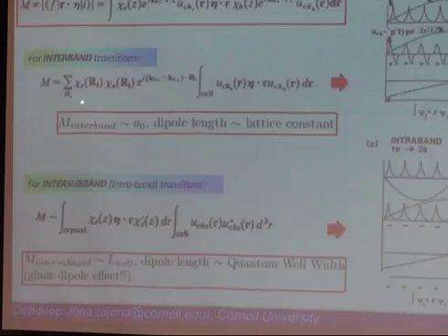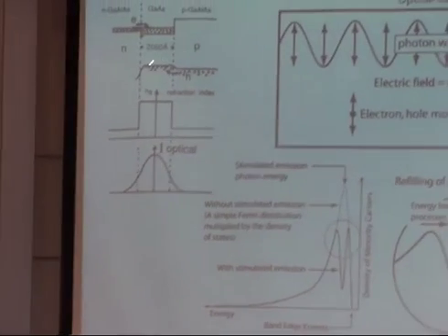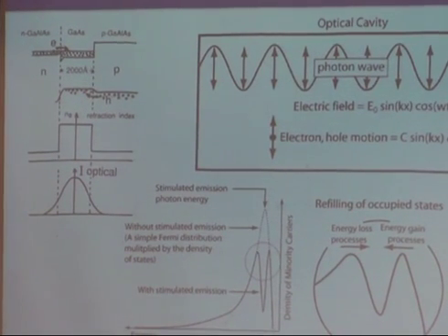Sorry, I'm going to skip a couple of things here. The other thing is I didn't talk much about mirrors, but I think you realize that if I have, say, a quantum well like this, a very thick well, it's not even a quantum well. It's 200 nanometers of gallium arsenide, 2,000 angstroms. These used to be called the DH laser, the double heterostructure laser. There's no quantum well, but you have two heterostructures.